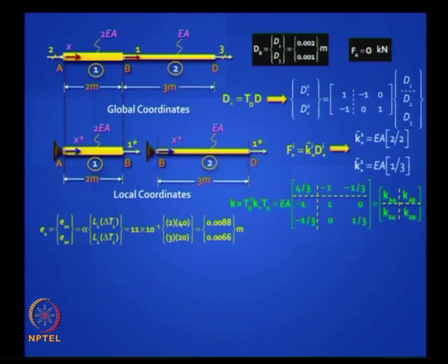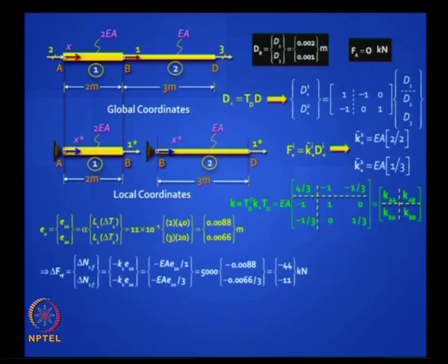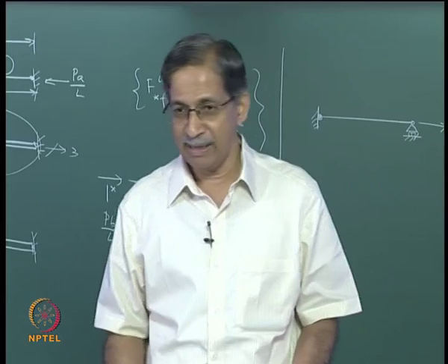You got E naught and then you know that this will induce axial compression of 44 and 11 kilonewton. We got these numbers last time also, remember. In the first element you get a 44 kilonewton compression, second element you get 11 kilonewton compression. So you can do this calculation directly. Always use your common sense, do not use formulas. You should get a feel for the problem.